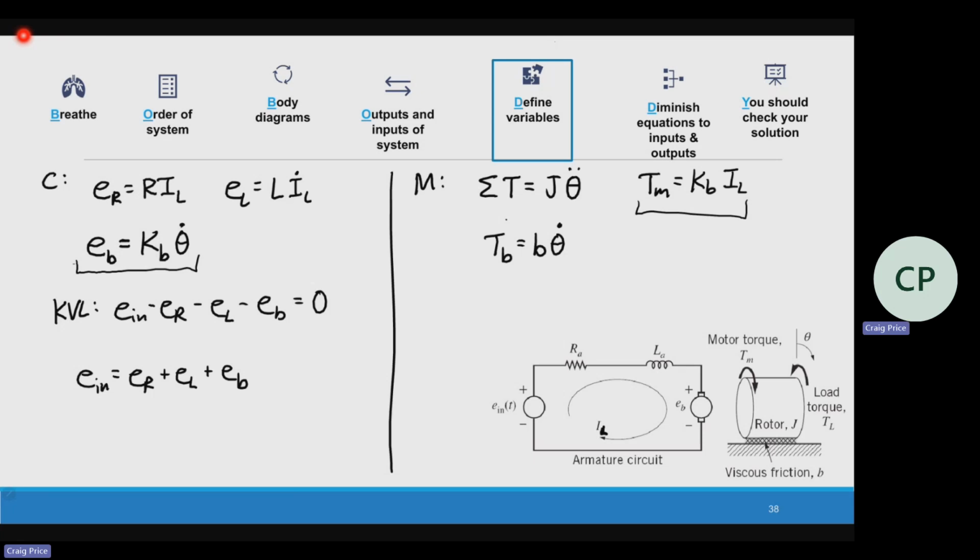Okay, so we're going to go to the next slide. We're going to put it all together, and then we'll build this in Simscape because they've got a DC motor block. I'm going to take this and plug stuff in. We're going to get one first order equation for the circuit. Wait, this is first order. This is second order for the motor. So in total, third order. You don't have to understand electromagnetism. Does this make sense? Just those two definitions tie it together.